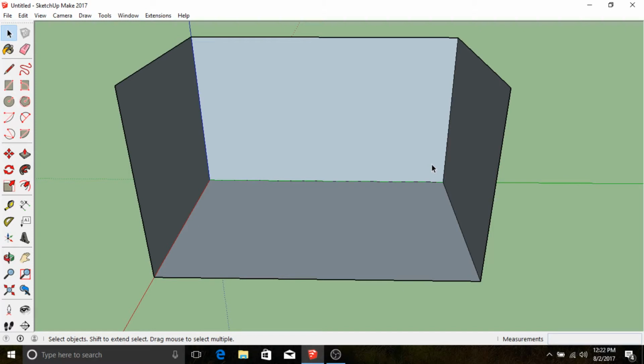Now I'm going to start with what's along the walls, and in this case it's going to be the windows, and then we'll get to the cabinetry. So to start with these windows, we are going to use the tape measure tool. We're going to go over from this edge 4 feet. So again, our default units are inches, so we have to put in feet, or we could put in 48, right, if we didn't want to put the units in? 48 inches for 4 feet. And in this case, the top of the window comes down 1 foot 7.5